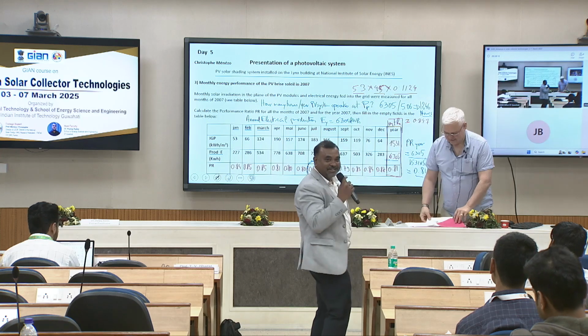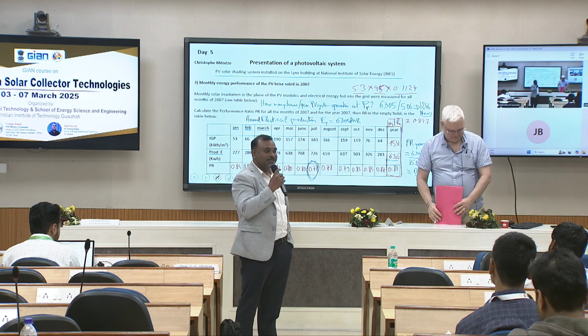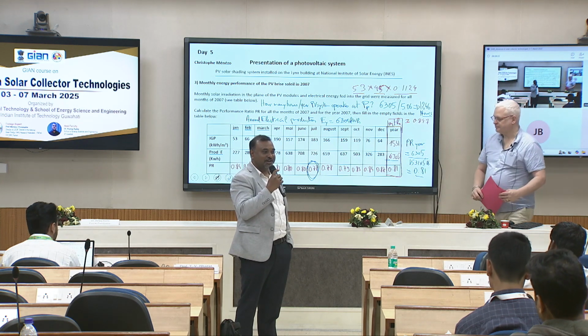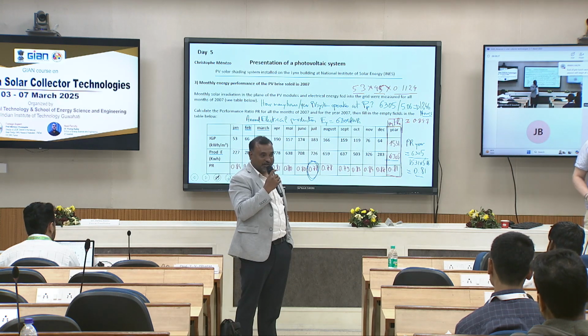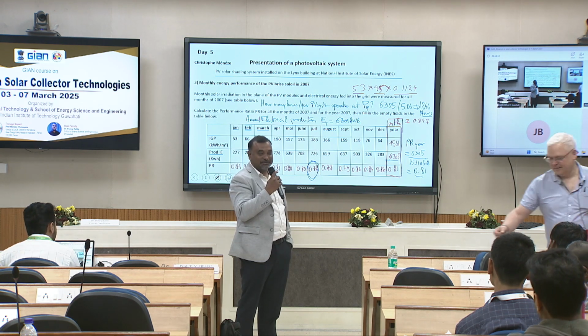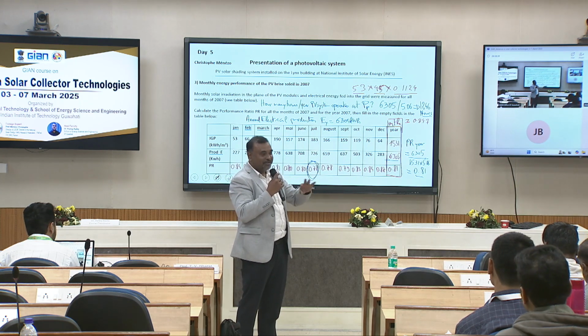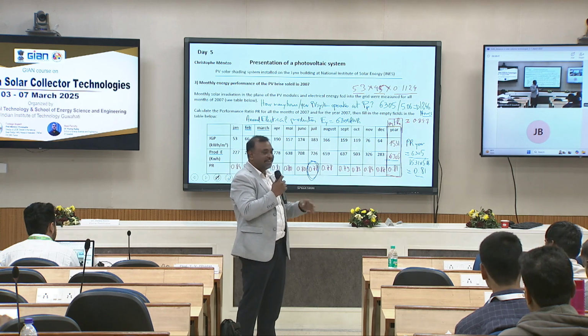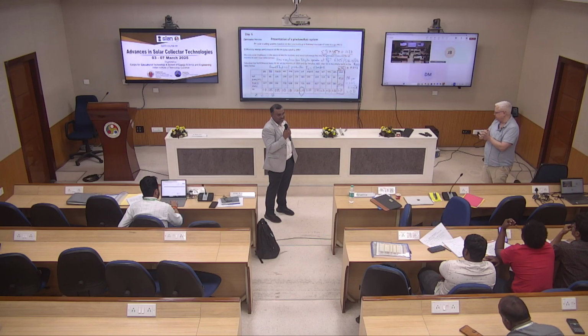It's a very interesting session, right? Everyone participated, and now you know how to investigate the performance of a solar PV power plant, and how temperature plays an important role. Even though we think that in summer it will work best, it does not; it's winter. But at the same time, we need to check the cloud cover and whether snow is covering the panels. Then again, we will not get that much radiation. That is also important.